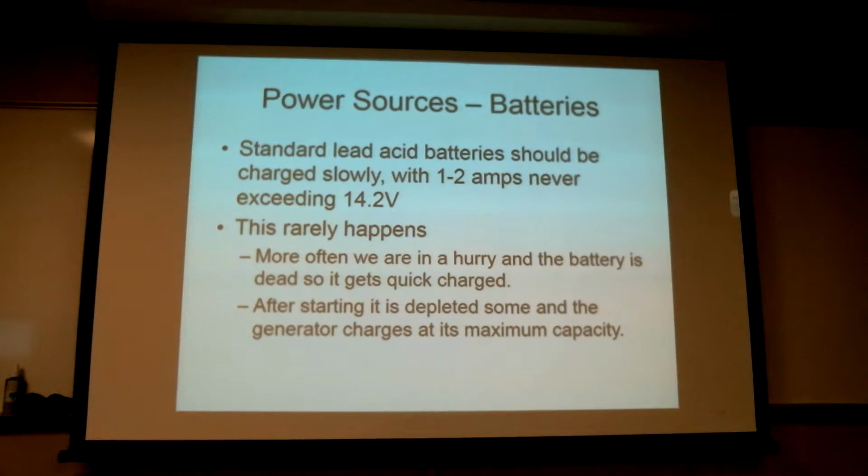Be at a low idle, so your alternator is actually not producing a lot of power. Then bring it up to a high idle, and let it run for about 5 or 10 minutes, charging, getting some juice back into the battery of the disabled vehicle. Otherwise, when you disconnect that battery from the charging vehicle, you're going to have an alternator dumping out way more than its capacity.